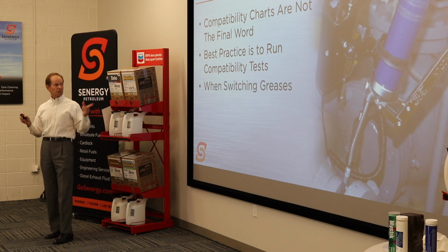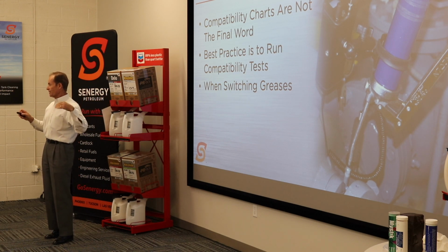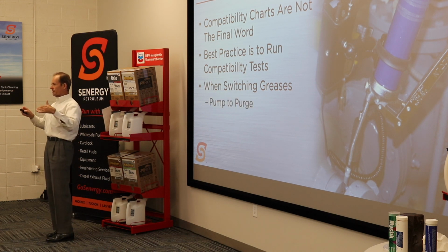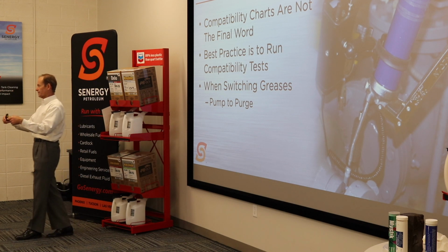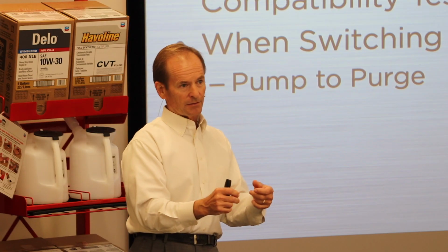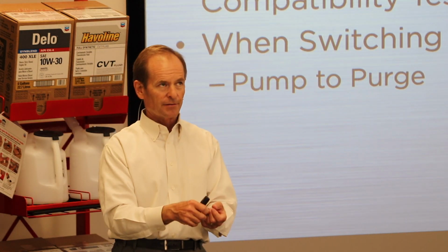Because when you switch a grease, you still can switch greases without running compatibility tests. Okay? But what you do is you pump your grease in until you get the old grease coming out. This is easier when you've got greases of 2 different colors going on, right? You're pumping in your red grease, chasing out your blue grease. You get a pretty good idea when you got most of it out of there.